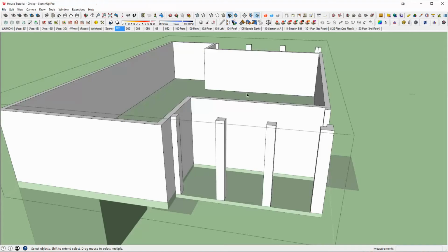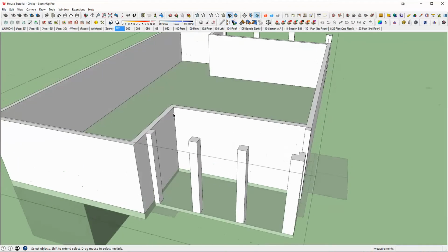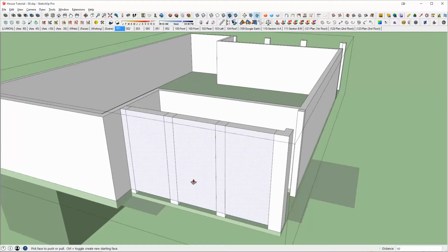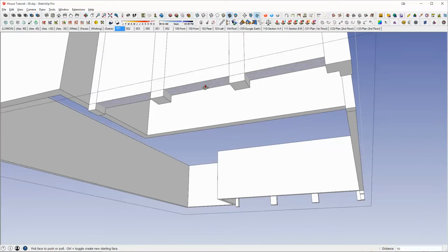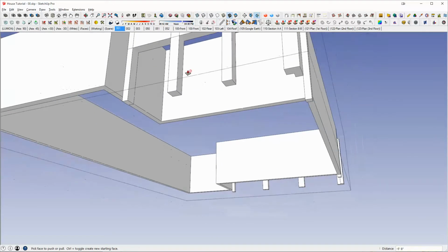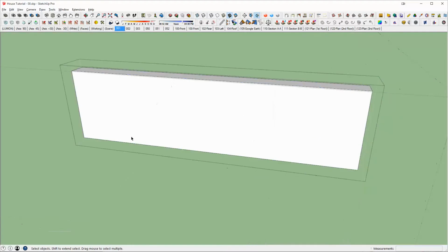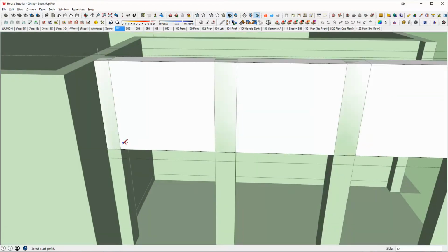So then going back to my SketchUp, I'm going to draw this down to my floor line, push it up 5'8". I'm going to turn this into a group. I'm going to show my model this time, and now I can do an arch, which should be 2'4", and looking down here, you'll see that the length verifies it's 2'4".